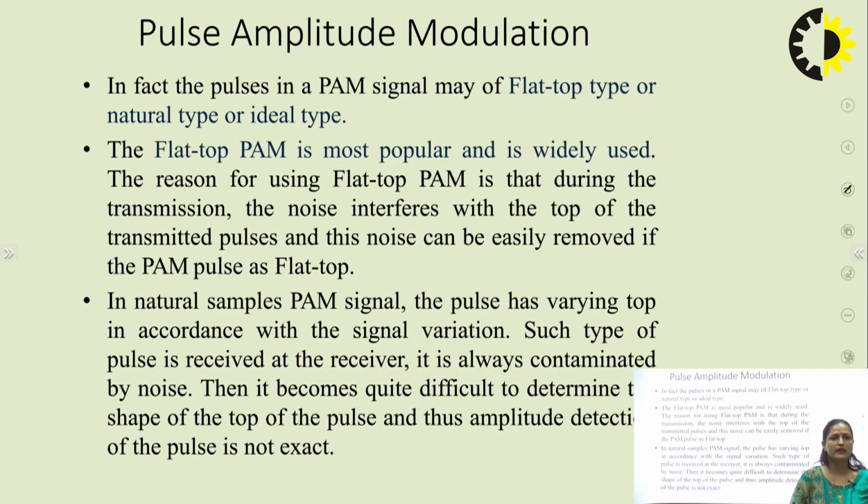In fact, the pulses in a PAM signal may be of flat top type, natural type or ideal type, any type, but we prefer flat top. Flat top PAM is most popular and it is widely used. The reason for using flat top PAM is that during the transmission, noise interferes with the top of the transmitted pulses, and the noise can be easily removed if the PAM pulses are flat top.